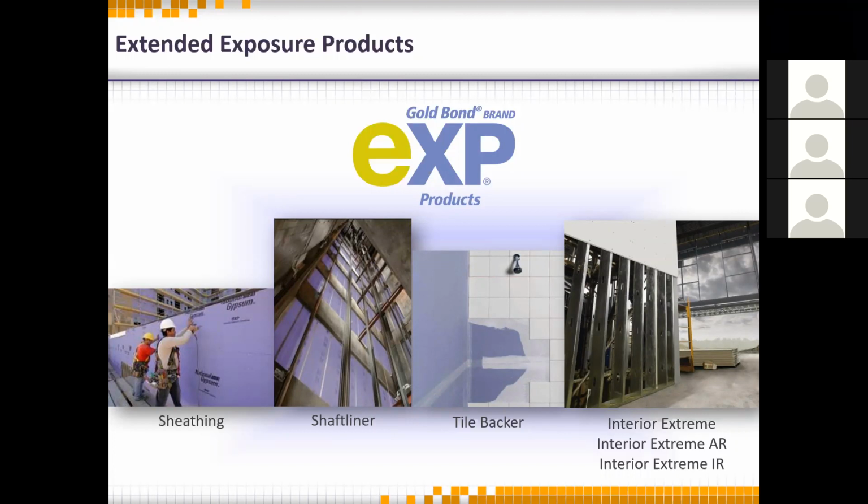And then the last picture on your right is very important if you're working on a building and it hasn't been topped out, hasn't been enclosed, isn't conditioned. You don't want to use just regular paper-based products in there because that will not necessarily conform to ASTM C840, which lays out the interior conditions that are needed.